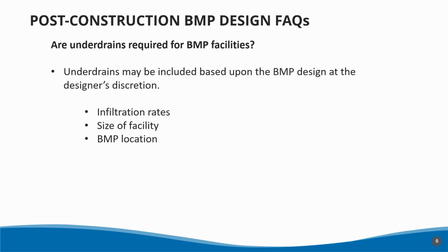If you do have underdrains, as John mentioned, maintenance is a big concern. So make sure you consider the type of perforations that you use, as well as including cleanouts, so that it can be monitored for the amount of sediment, as well as be used as a cleanout point of entry.